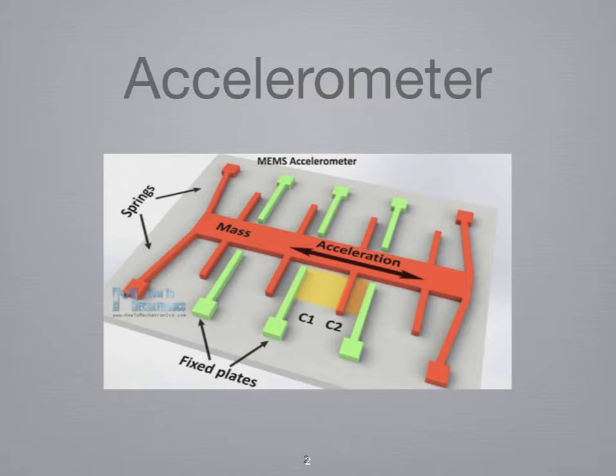Fiber optic devices are particularly attractive and can give measurement resolution as high as 1 micrometer. Unfortunately, there are considerable practical difficulties in mounting and calibrating displacement and velocity transducers, and therefore they are rarely used. Because of this, vibration is usually measured by accelerometers at all frequencies. The most common type of transducer used is the piezo accelerometer, which has a typical inaccuracy of plus or minus 2%.